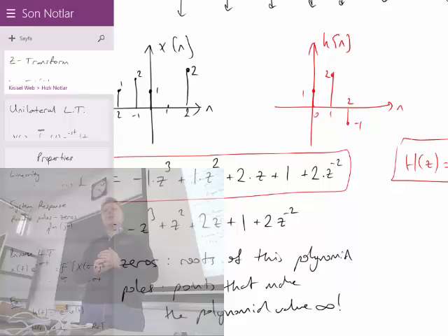Furthermore, let's do some more signal processing. They do MATLAB convolution not with an algorithmic convolution because it's a slow operation for long sequences. If both of the sequences are quite long, then it's not worth it. There is a faster way of implementing convolution. Can you imagine what? They apply the so-called discrete Fourier transform, which we haven't seen. We have seen the discrete time Fourier transform, but we didn't see discrete Fourier transform. It's a topic of digital signal processing. We're not going to cover that.